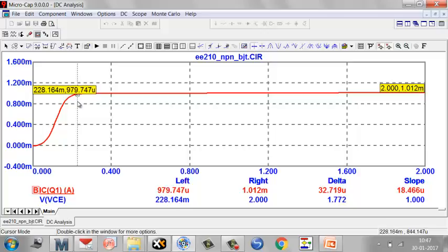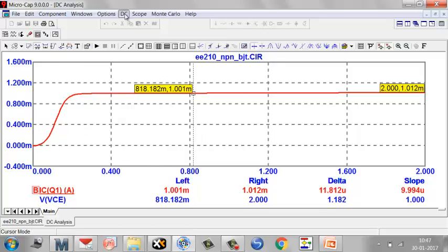Not really 0.2, right? We are saying it's beginning at 0.228. At 0.2, you're somewhere here, already into saturation. So what we are taking is not really correct. We should take a little larger. Okay? And then if you go further, then you see this is what happens. All right. So anyway, this is our transistor.